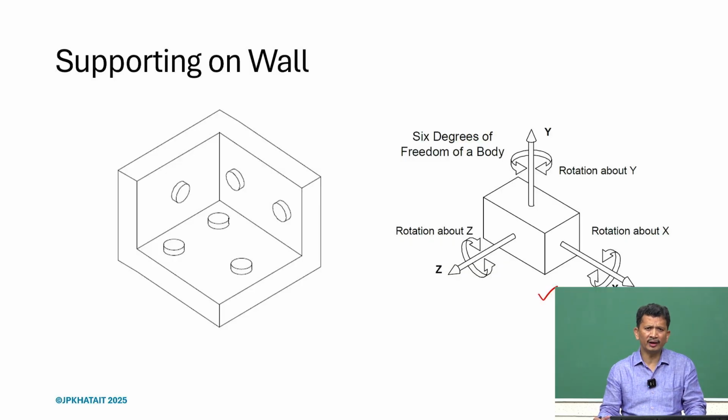I think what we realize is that if we understand kinematic design or kinematics, we may not have to do that. Just by defining the contact points, we should be able to constrain it properly. And then what we have to emphasize is to focus on designing those contact points or contact surfaces.